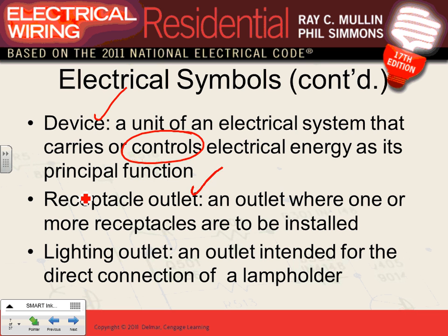Receptacle outlets is an outlet right in front of you. At the end of that outlet there is a receptacle. You guys are all familiar with the receptacle 120. The receptacles can be 120 plugged in or twisted type receptacles. Nema has tons and tons of receptacles that go from 15 amp single phase 120 into 100 amp 480 3-phase. So most of us think of receptacles as these little ones. As we move forward, you're going to understand there are 3-phase receptacles too. Any question, guys, about receptacle outlet? An outlet that ends up in a receptacle, or a receptacle at the end of that outlet.